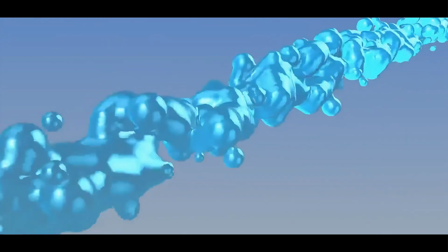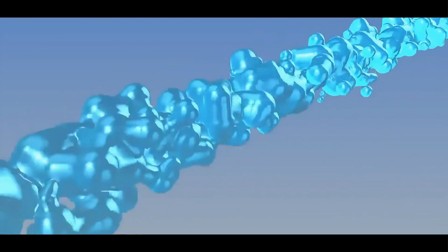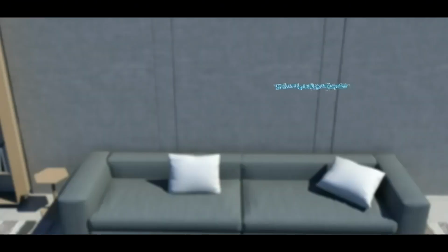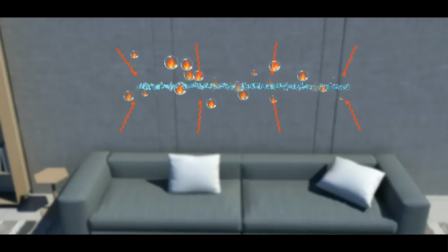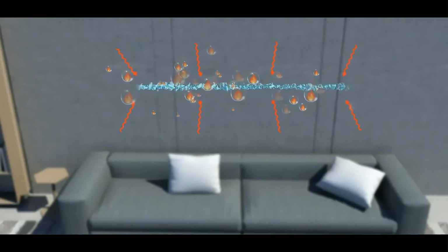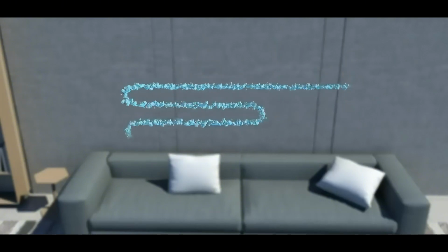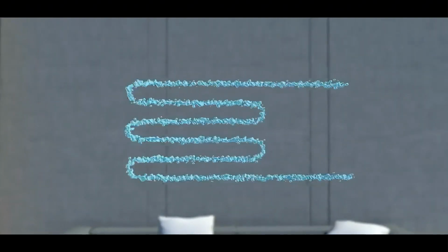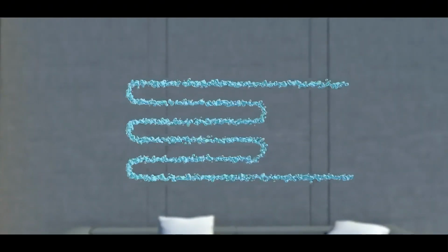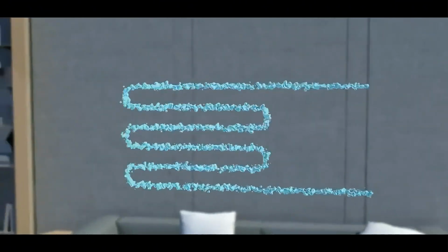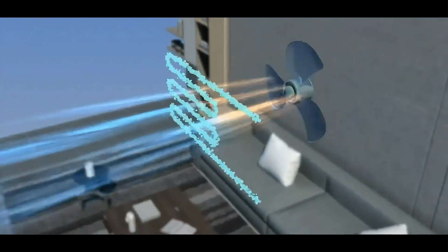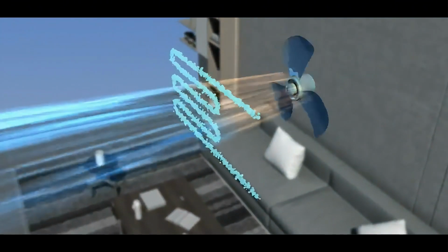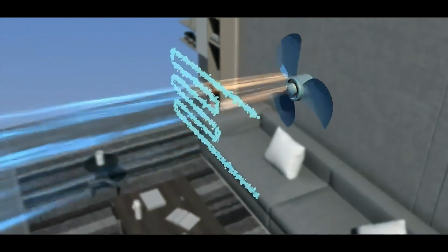An air conditioner uses refrigerant with large evaporative latent heat. Let's assume a refrigerant in a hot room. The refrigerant will take away heat from its surroundings to evaporate. If we enlarge the area of contact of the refrigerant to the air, the refrigerant will take away more heat. When we blow wind from behind the refrigerant, air that lost heat becomes cooler, and the cool breeze comes out from the front.